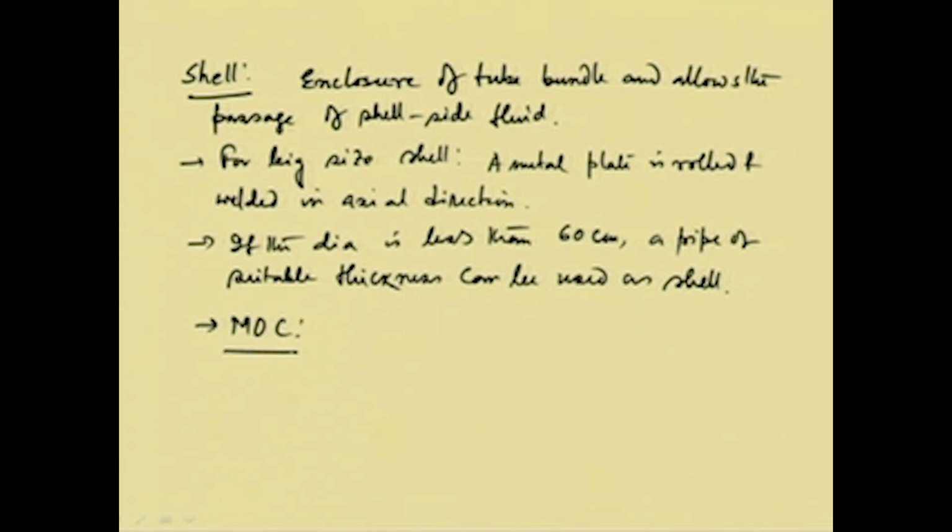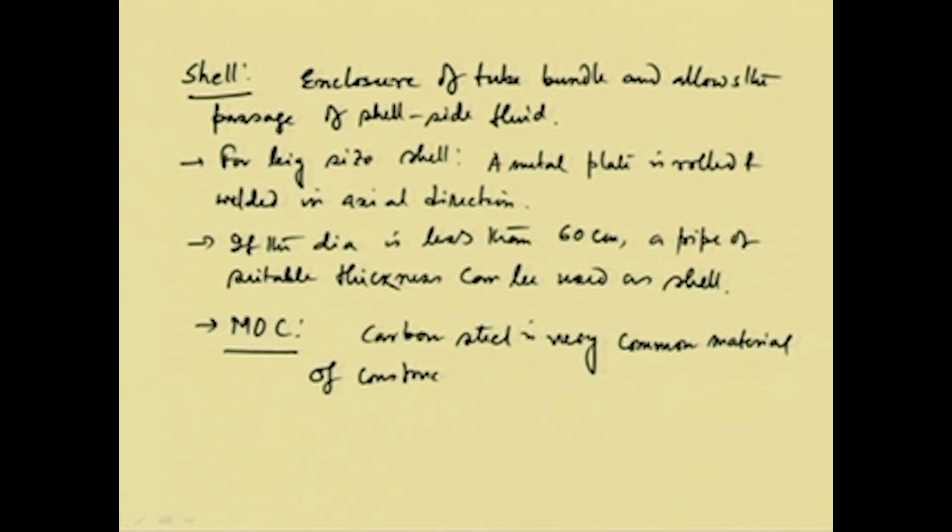Material of construction, MOC, is usually carbon steel, which is a very common one. Now, the material of construction is definitely dependent on the operating conditions and also the fluids to be used. Operating conditions mean temperature and pressure.